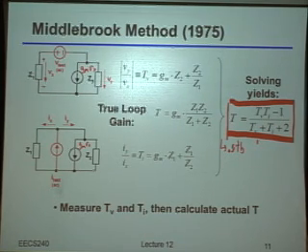Yeah, exactly. By the way, you have to be careful when you say big and small, because in some cases, making the parameter number small is actually more accurate. But basically, you'd crank up the accuracy of the simulator, or to be more clear, you'd run a simulation with whatever your default setting was. And then if you're not sure if it's really accurate, you say, let me crank up the accuracy. If you crank up the accuracy and you see that nothing really changed, that's a pretty reasonable indication that things are reasonable, right?